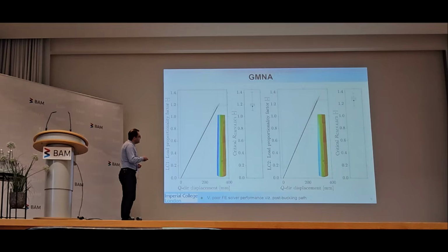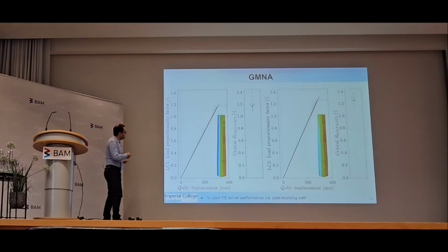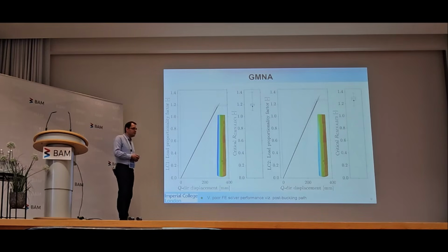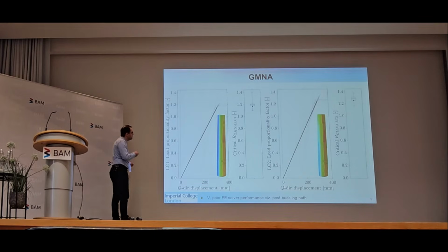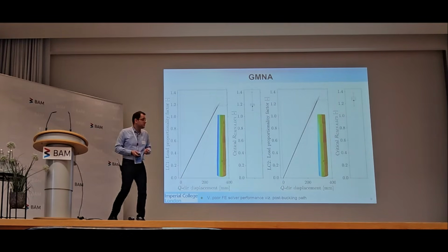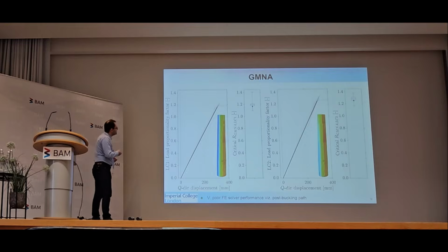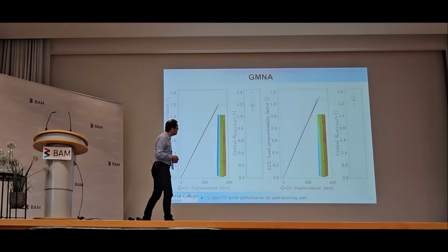This one, the variability here was surprisingly small. These analyses, yes, they will be affected by plasticity, but you will never get very far into the plastic range for any strain hardening that you may have assumed to matter all that much. So this will buckle, the buckling mode is relatively localized, and as soon as the buckling region begins to yield, it will just fail, it will just buckle. And so mostly these results are close for both LC1 and LC2.